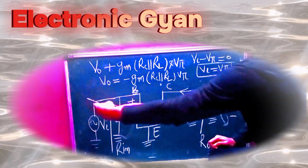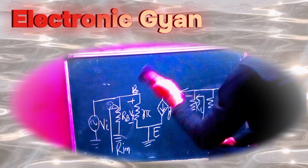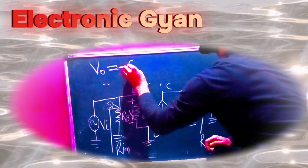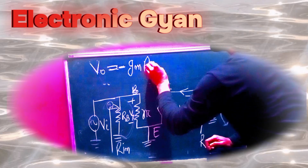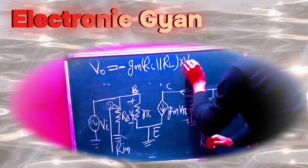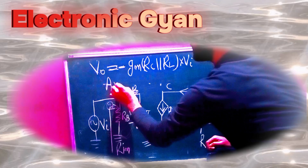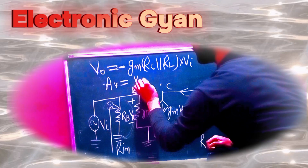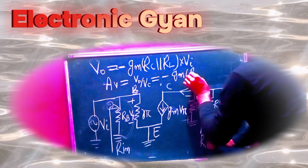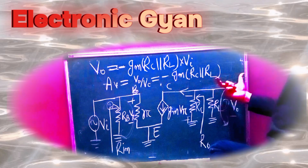So let's see, I'm going to again remove this. Finally we get the voltage gain as, if you see here, V0 is equal to minus gm into RC parallel RL into Vi. So therefore my voltage gain AV is equal to V0 divided by Vi is equal to minus gm into RC parallel RL. Yes, RC parallel RL. This is my voltage gain.